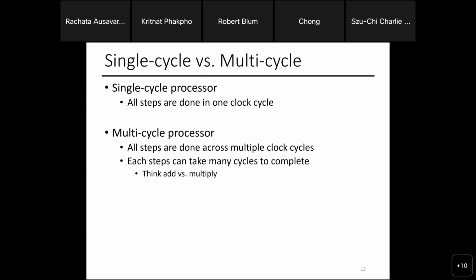These allow you to, for example, let's say I have an add and a multiply. I can separate out the two commands. If I just do an add, it'll be a few cycles and I'm done. If it's a multiply, a lot more cycles. If I have to access the memory, it's even worse, right? Because you have to go to cache and so on. That takes a long time. That way, an add instruction will not be as slow as the memory instruction.